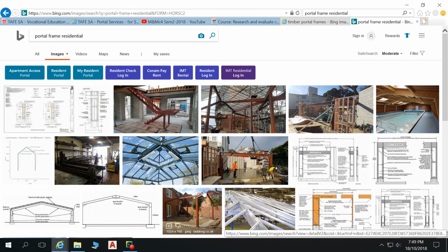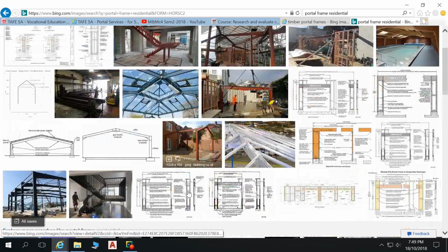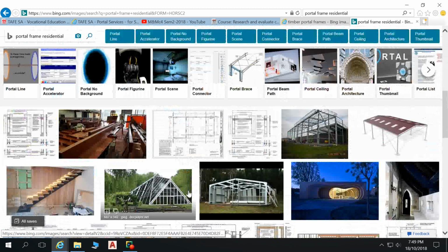But you can also, like they've got here, hot rolled portal frame. Okay, so that's going to be expensive. That's not going to be cheap. Your cheaper option would be to have this light gauge stuff welded together. But with your hot rolled stuff, your depths of members can be much smaller, and so you can do slimmer, more elegant walls with that. Something that has a bit of magic to it.